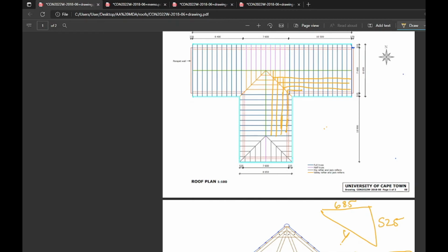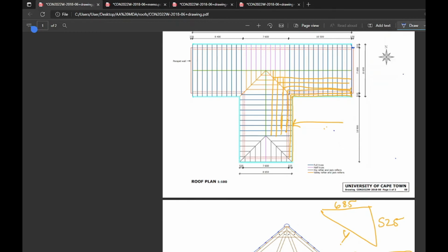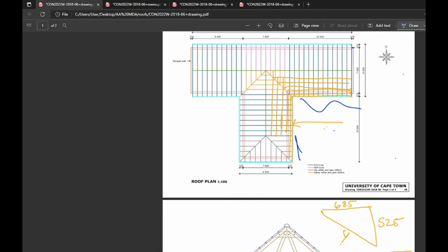So, what we want to know is which pieces of timber will be visible to the world, and how do we treat this timber? If you are lazy, you might leave it and say there's nothing wrong with it. No one's going to see it, I don't mind. Maybe there's bushes and trees here, who knows. But in this case, and I think for most cases, we will assume that you want it wrought. Exposed eaves, basically. Because, well, that's what this assumption is.